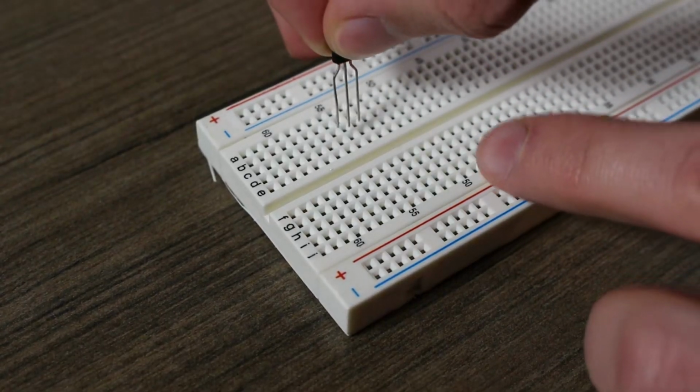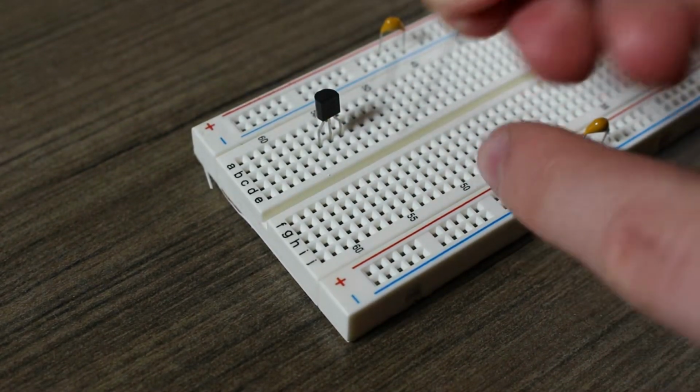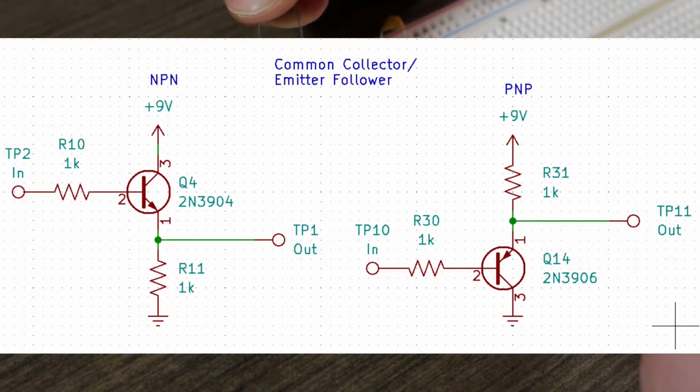There are three basic types of BJT configurations: common emitter, common base, and common collector. Let's start with common collector. The common collector configuration typically has the collector connected to the positive rail for NPNs and the negative rail for PNPs. The emitter has a resistor and the base has the input signal.